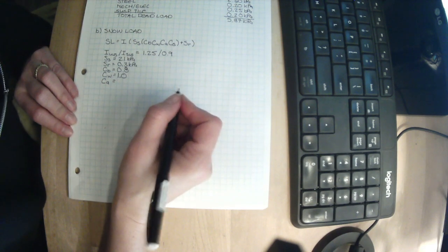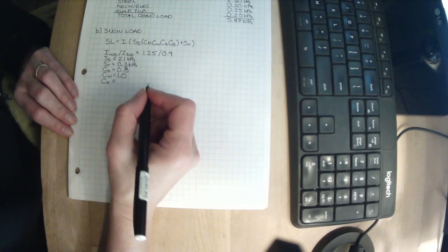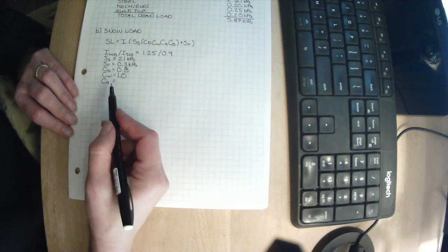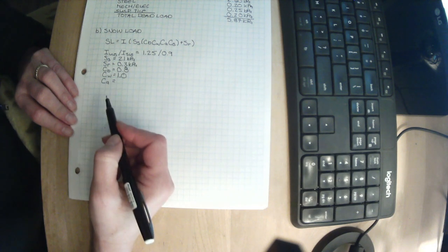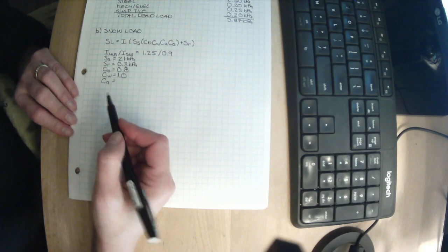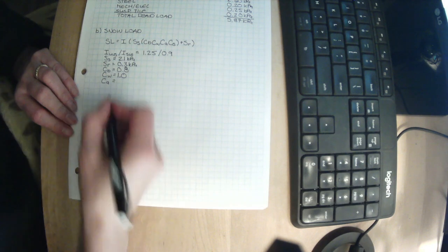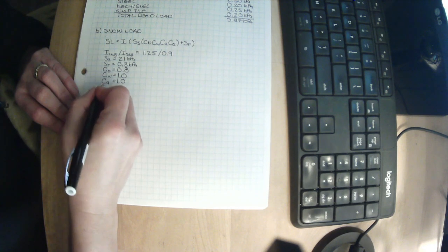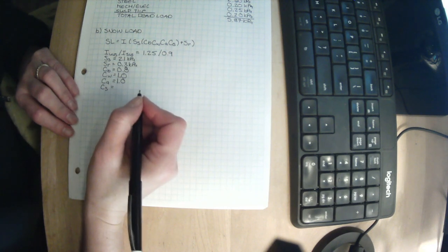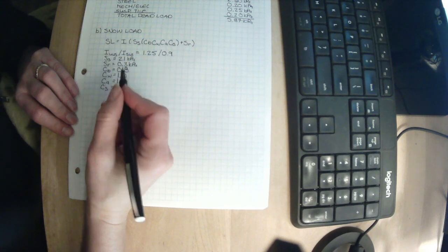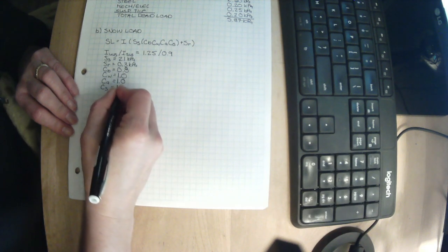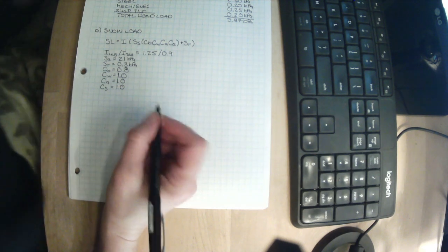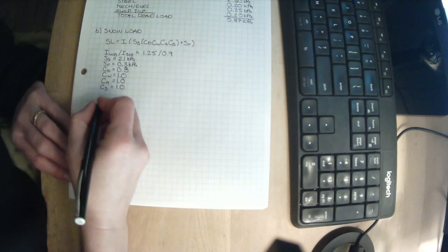CA is our accumulation factor. Now, we don't have any buildings around it that would cause accumulated snow load to pile up on our building. It didn't say anything about a parapet. We would worry about a parapet if it was there, but it didn't say anything about it. And then CS is our slope. It didn't say it wasn't a flat roof. It looked like a flat roof looking at the design of it. So I doubt there's any way we could slide any of the snow off that roof. So it looks like we have all of the information we need.